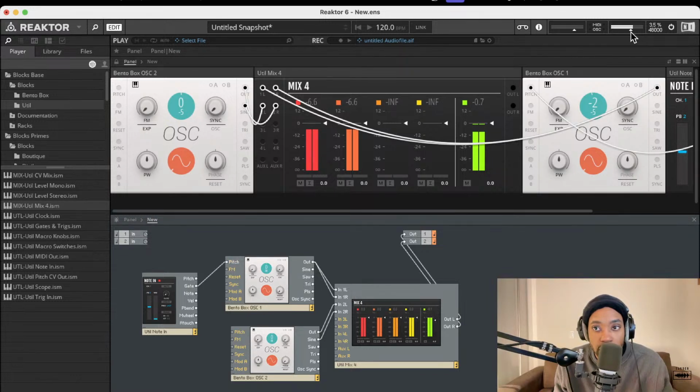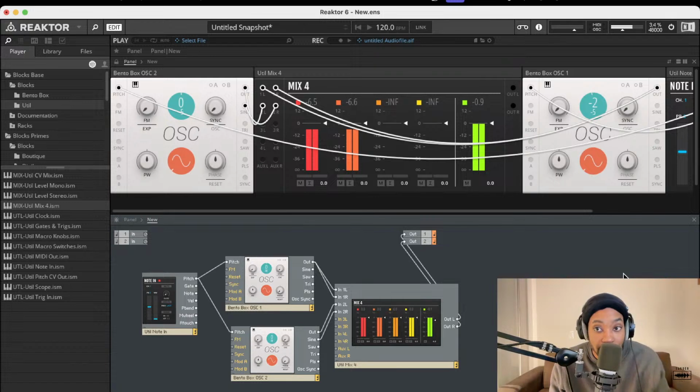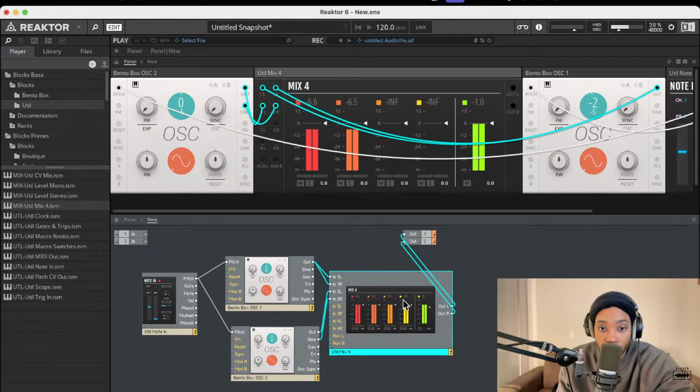Before we do, let's turn down our volume so we don't burst our eardrums or cause hearing issues. It's important to protect your ears when you're working with loud sound, especially unfiltered loud sound, when you're working with raw waveforms. Always keep the volume at a low level, so if any pops or glitches happen, you can be aware. And before you enter any signal, you want to either mute or turn down the volume before you patch, so that you can control the volume.